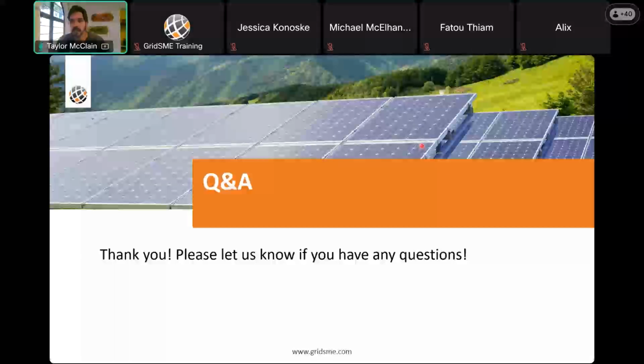So there are so many different aspects to test from this, but the root of it all is that it reflects the design characteristics you have chosen for your project so that the ISO or PTO can effectively determine what those impacts are, whether it be with power flow, dynamic stability analysis, short circuit analysis, EMT modeling. It all is done so that they can say, hey, you're going to build your project in this way. We'll tell you what those impacts are.